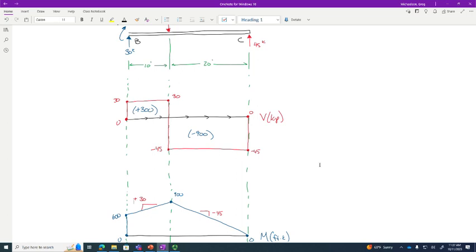With trusses, remember, we looked at all different ways we could analyze a truss, a method of joints, a method of sections, and then we looked at deformations. We looked at how much a truss would deform under applied load. And if you remember, we had a method of doing that, the method of virtual work, or the unit load method, right? So we would analyze the structure twice. We would analyze the structure with the loads as is, and then we would do a virtual analysis.